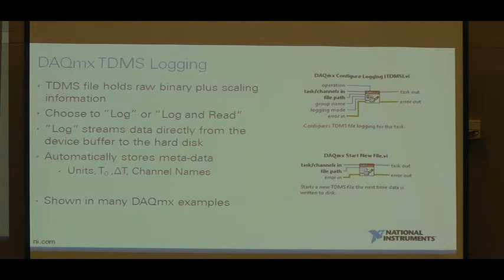Some of the metadata that we store automatically: we store the unit for every channel, we store the initial timestamp, we store the time between samples, 1 over your sample rate, and we store the names of all your channels, or if you haven't set the name, we store the physical channel name. So I'll show you.